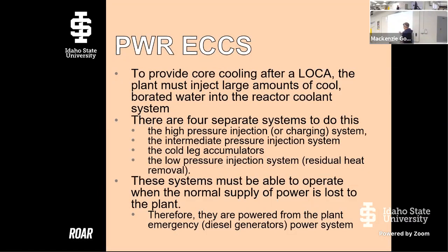One interesting thing, this low pressure injection system, is essentially assuming that the pressure conditions inside the reactor have degraded, right? So it's no longer held at a pressure. And you hope that this occurs when you've cooled your reactor enough from its initial power and heat condition that you're just dealing with residual heat removal. This was one of the big things at Fukushima, right?